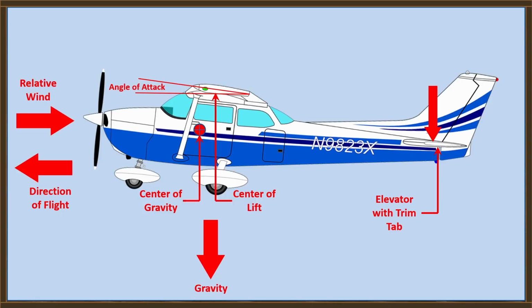Okay? No, it's not okay. It is not the thrust that controls the pitch of the airplane. The pitch of the plane is determined by the forces applied to the tail of the plane. If airflow across the tail, across the elevator, is pushing down on the tail, that will lift the nose of the plane. The plane will rotate about the center of gravity in the pitch axis.